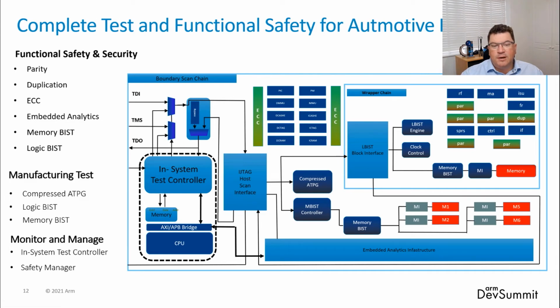All of this test technology, both the BIST and the manufacturing test, sits on an industry standard architecture, the IEEE 1687 IJTAG. This is then hooked back to the industry standard tap controller with the regular tap interface that goes to external pins. However, internally, the interface can also be intercepted by the in-system test controller, the mission mode IP. The mission mode controller intercepts the tap pins and is able to deliver the test sequencing information and test setup information required for those tests when running in system mode.